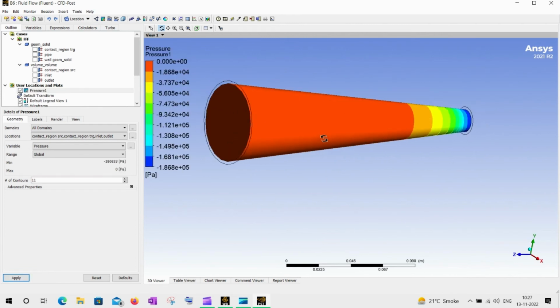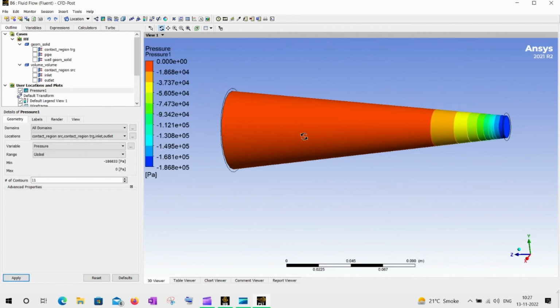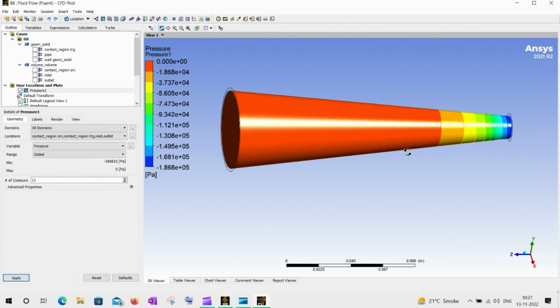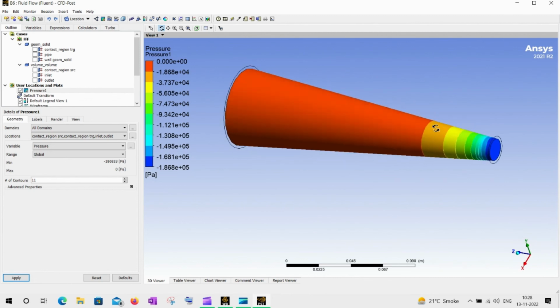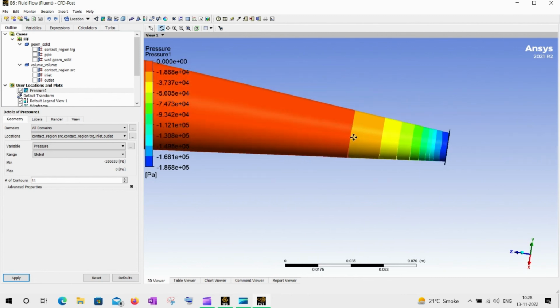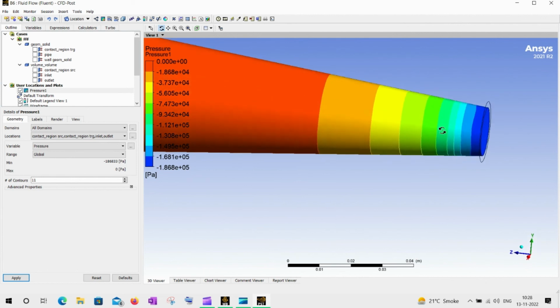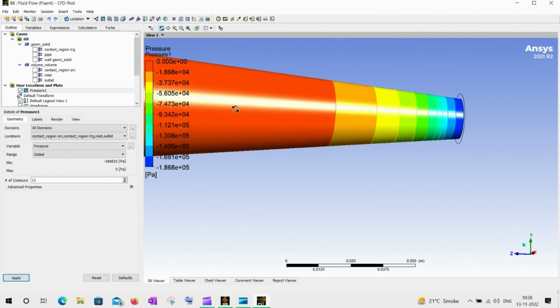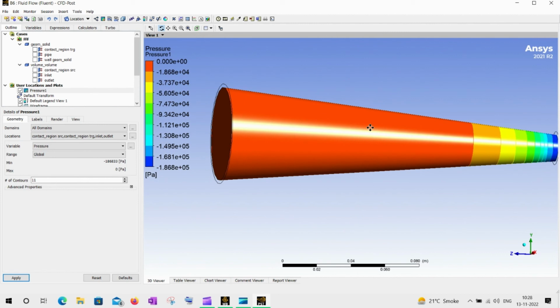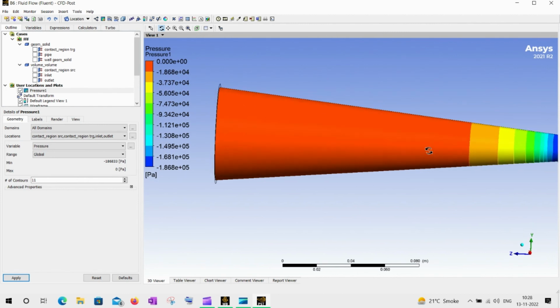We can see very clearly what has actually happened, and this is why CFD Post is required. You can see how easily we can see where the flow is getting disrupted, and for only less than half of the pipe's length, flow was able to maintain itself. It's very easy. If you go deep, you can also find your values here. You can see at this point we have almost stopped.